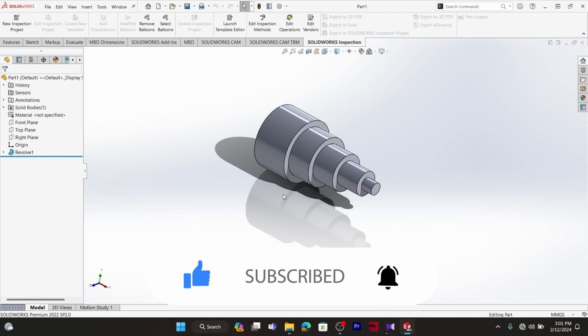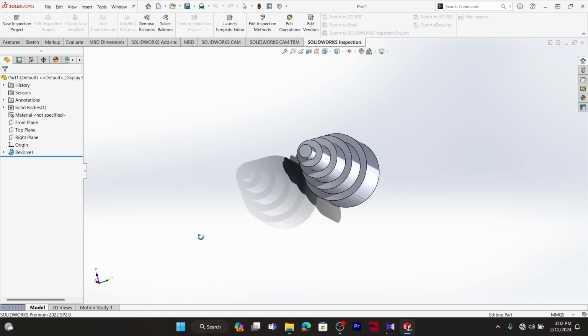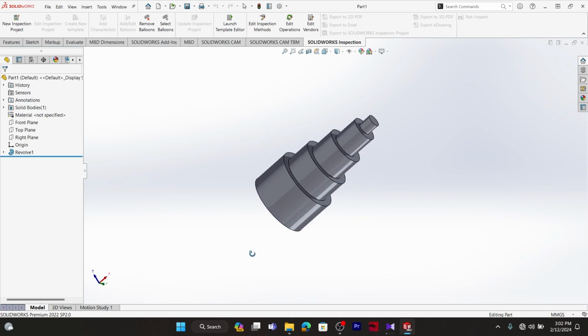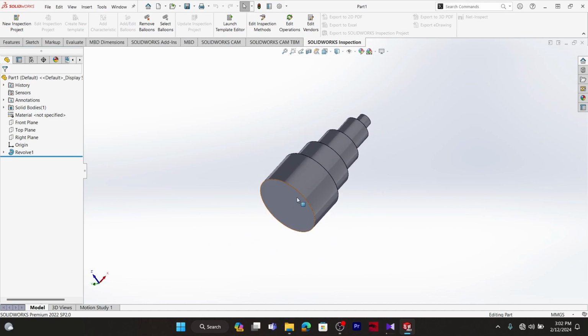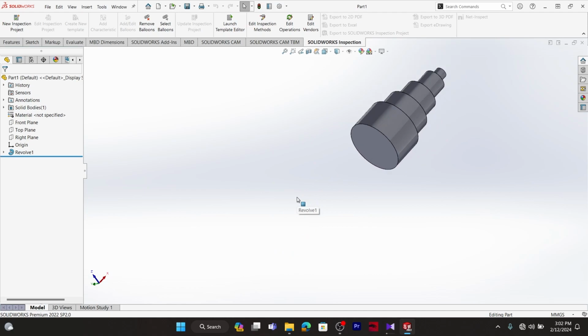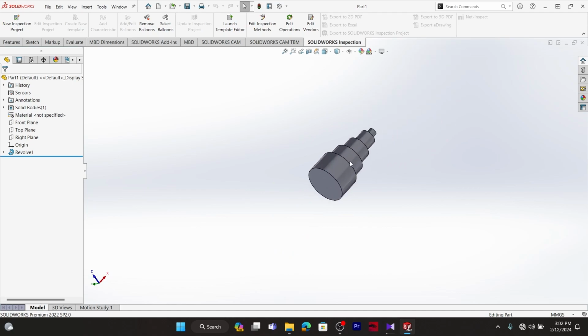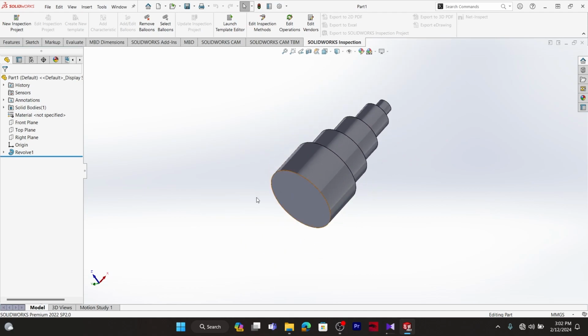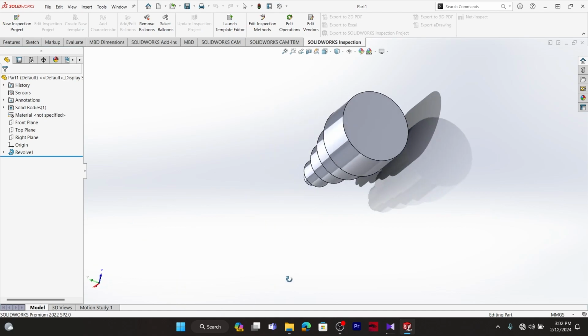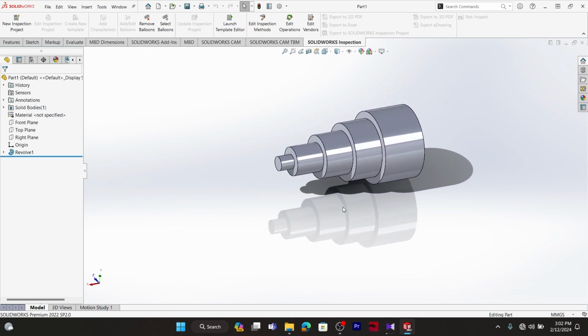Now moving on to this. I have a 3-button mouse, and here I'll just rotate my mouse wheel. If I rotate it in one direction it will zoom out, and in the other direction it will zoom in. Now as you can see, the drawing has moved out of our view area, so I'll press and hold my Control key, and then press my middle mouse wheel and bring it here. That way you can just pan your drawing.